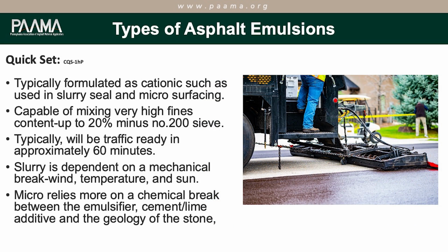We have quick sets, typically formulated as cationic, such as used in slurry seal and microsurfacing, capable of mixing very high fines content up to 20% minus 200 sieve, which again is that really fine powdery stuff. Typically this will be traffic ready in 60 minutes. Slurry is dependent on mechanical break, so wind, temperature, and sun. Micro relies more on a chemical break, being the emulsifier, cement or lime additive, and the geology of the stone.